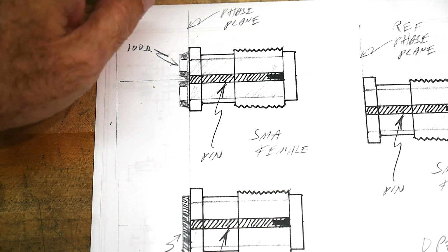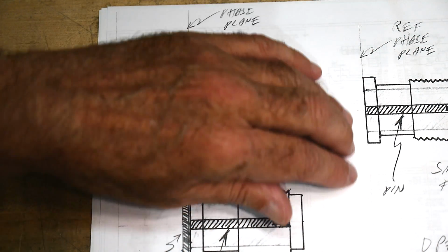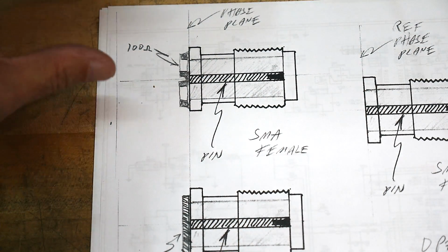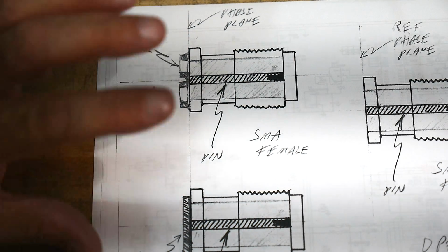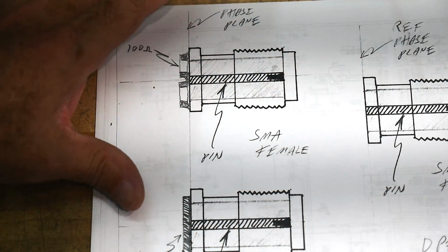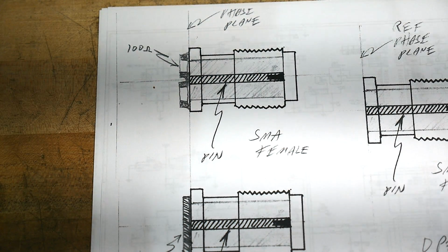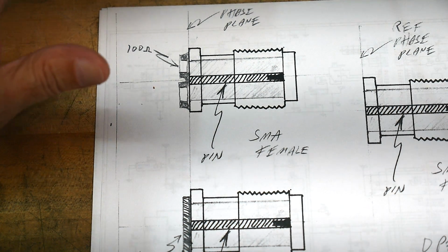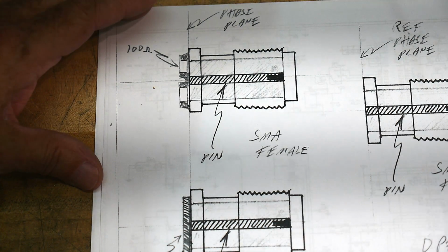They're machined very, very accurately to have exact mechanical phase planes, these reference planes. And that's a big trick. The connectors on the front of the instrument are super, super expensive. The equipment inside is super, super expensive to make sure that these reference planes are held really, really close. Now in the little NANOVNA, we're holding them within maybe a few picoseconds, but in a big VNA, you have to be much, much better than that.